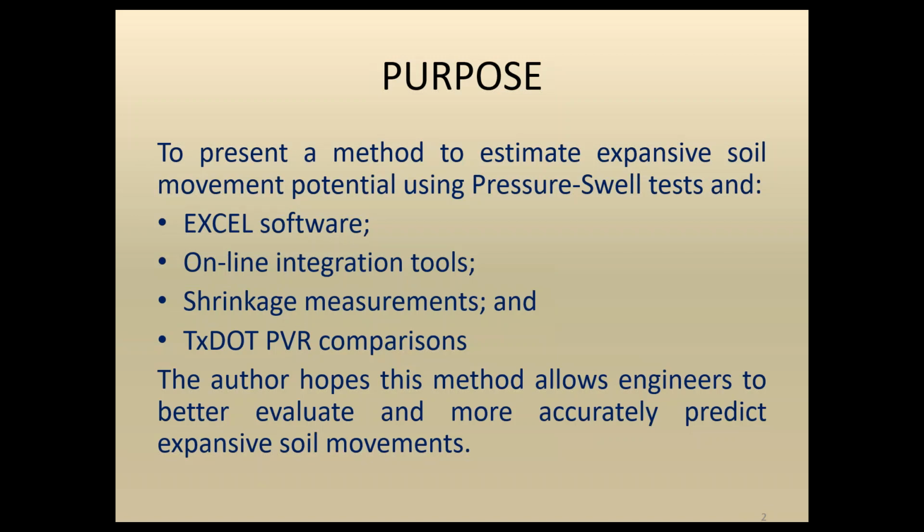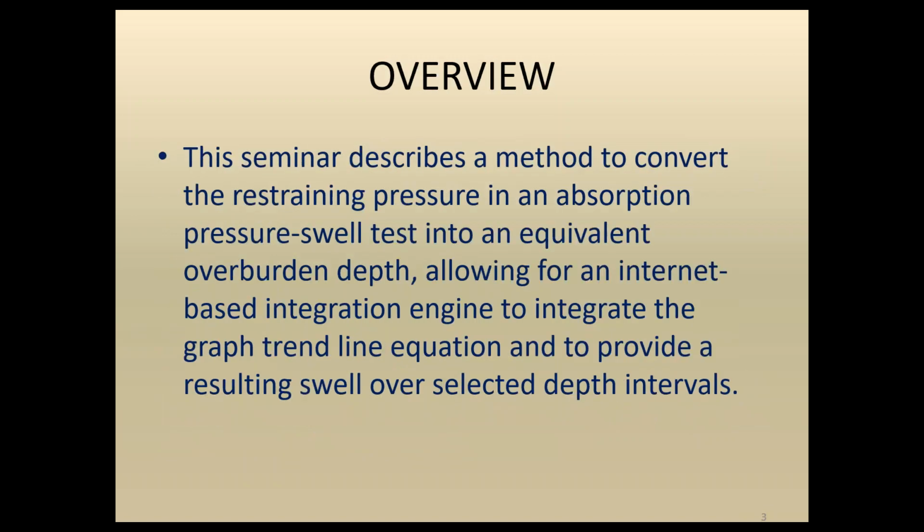The purpose is to present a method to estimate expansive soil movement potential, using the pressure swell tests and using Excel software, an online integration tool, using shrinkage measurements, and comparing results with the TxDOT PVR. The hope here is that this method will allow engineers to better evaluate and more accurately predict expansive soil movements.